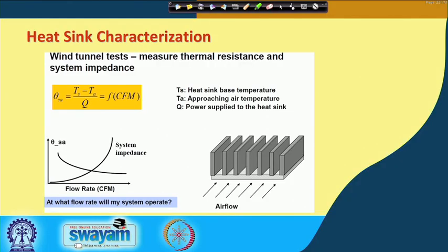Okay, so let us start with heat sink design and what it is. We have seen pictures as well as photos of heat sinks, and let us just consider a parallel plate finned heat sink like this. There is a base which is kept on the heated surface that I need to cool, and then there is air flowing through. This is a flow through mode, not impingement mode.